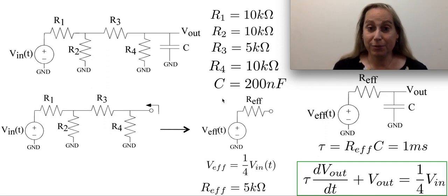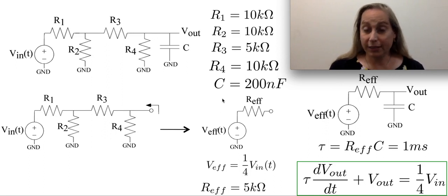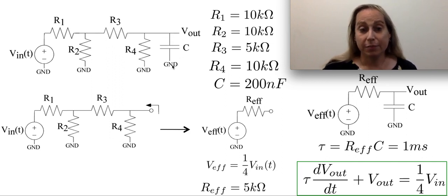I want to talk about a first order circuit, in this case with a capacitor and a bunch of resistors and a driving independent source, and to look at how we would think about solving these systems. Now the first thing, before we go any further, is to notice that we have one capacitor, and that capacitor sort of sets the conversation. That capacitor means I have one state variable, which really sits on this node. We're going to talk about ground being fixed, so it's really going to be related to this node, which is going to be the output voltage.